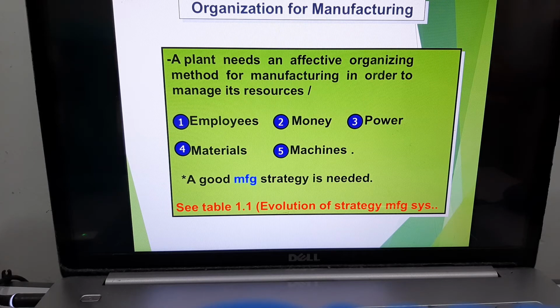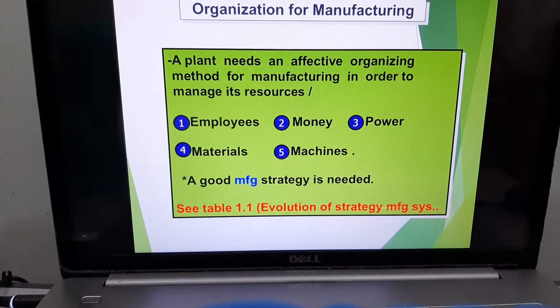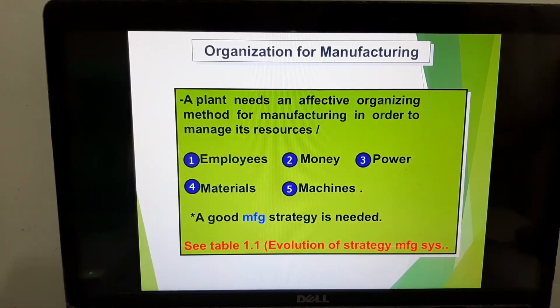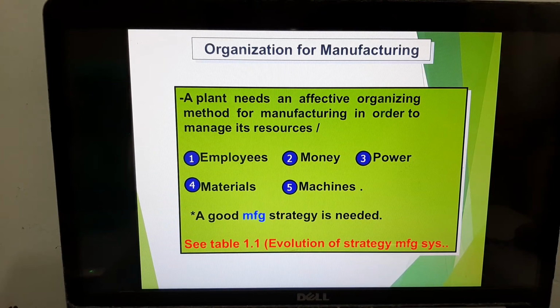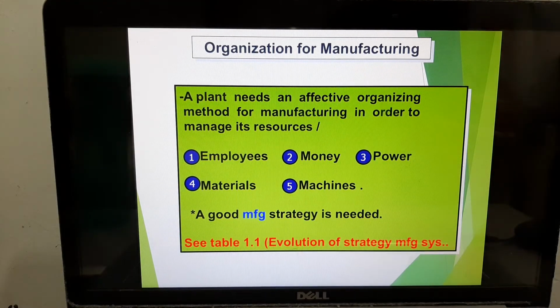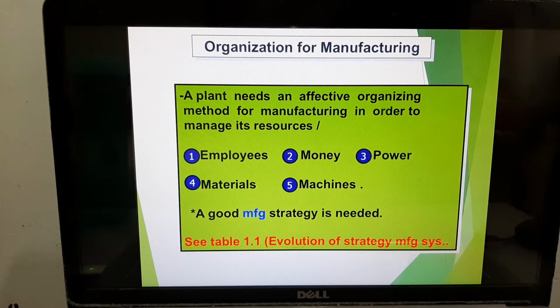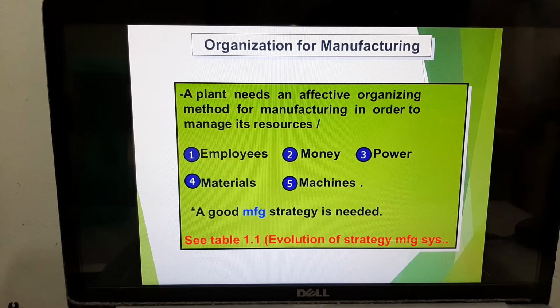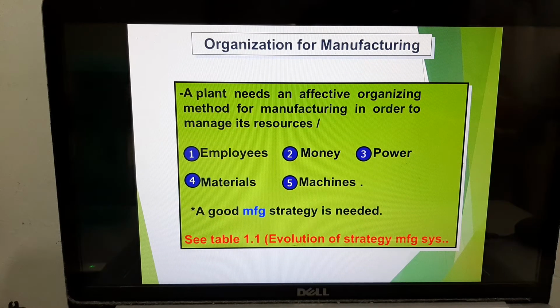Now as we continue, I spoke about production. There are three types of production: mass production, moderate production, and job lot production. You use mass production when you are going to produce a large amount of products, more than 100,000 parts a year. But normally mass production has a limitation whereby the product will not have any design variation. It's a standard design. For example, a bottle cap, a screw, a bolt, a nut, it comes with a standard design. You're not going to vary the design.